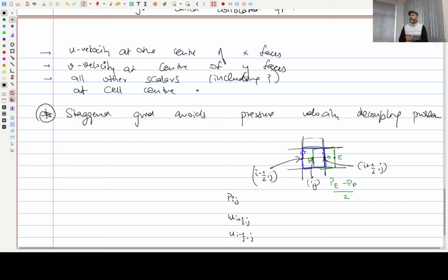So that is the actual problem with staggered grids: when you're dealing with complex meshes, it becomes very confusing how to use it. For simple situations, it's easy, but life is not as simple as this one. This was proposed many years ago to solve the pressure velocity decoupling problem. But when we got better machines available, we realized that we are solving very complex problems with complex boundaries and geometries, and the choice of staggered grid actually became a hindrance to solving problems comfortably. So then we came back to co-located. Nowadays we end up using co-located grids.